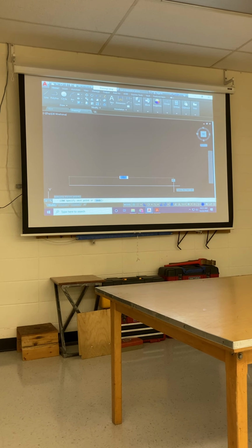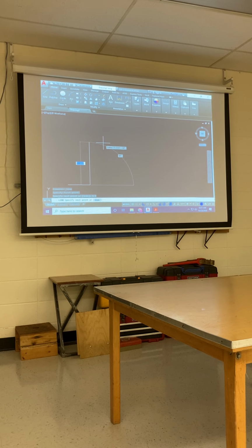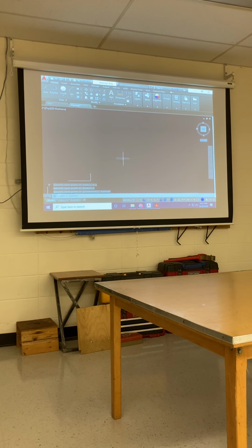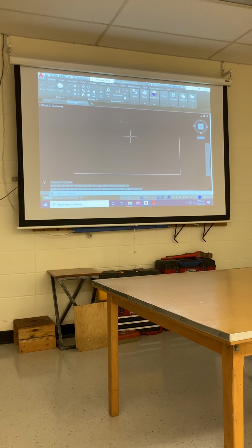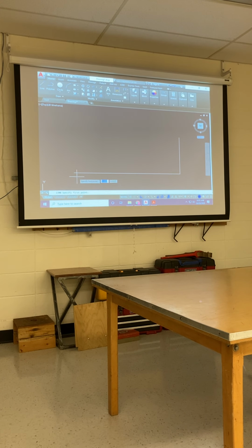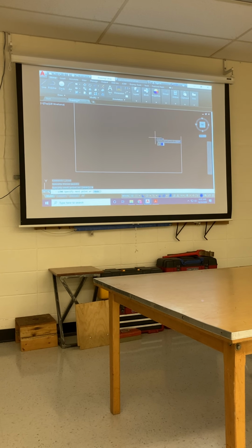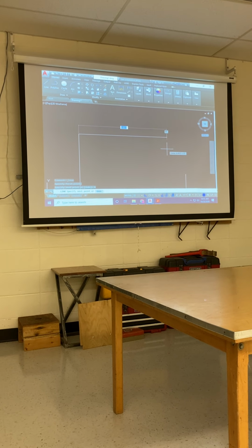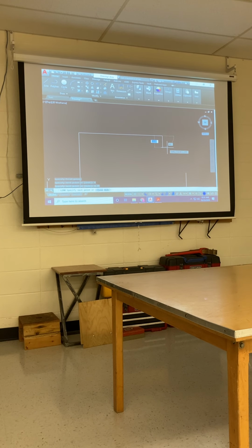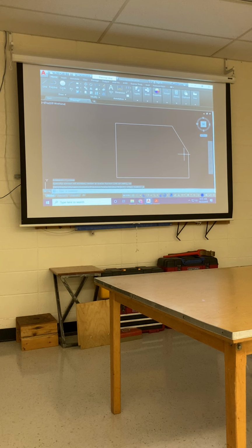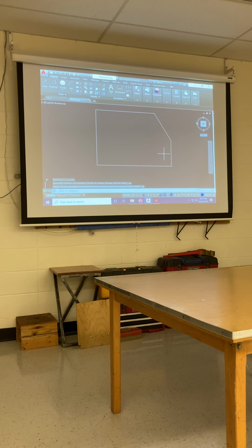That part is 5.5 long. It comes up this left side 2. Zooming out on it a little bit, it's a height of 4. So I'm gonna go up 4. I'm gonna go over to the right, 4.25. I'm gonna connect my left side. There is my outer extents.